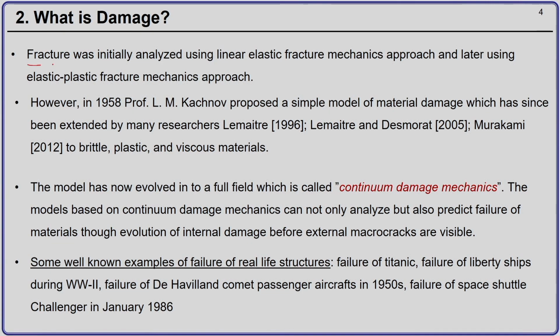Fracture was initially analyzed using the linear elastic fracture mechanics approach, and later using the elastoplastic fracture mechanics approach. Linear elastic fracture mechanics is called LEFM. This is still very popular, where we find the stress intensity factor, J integral, and all these kinds of concepts.